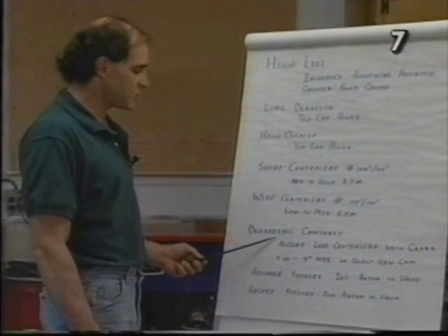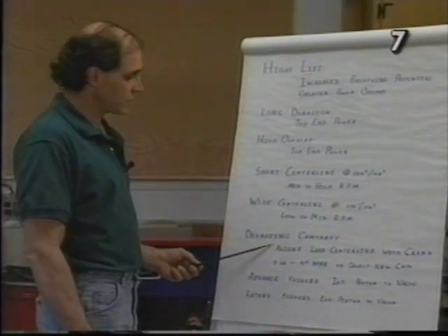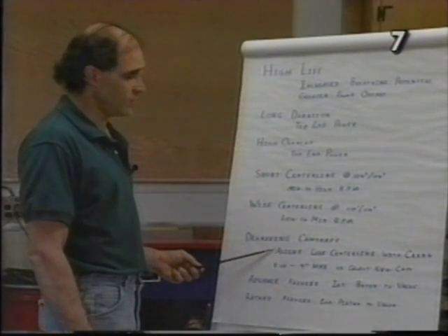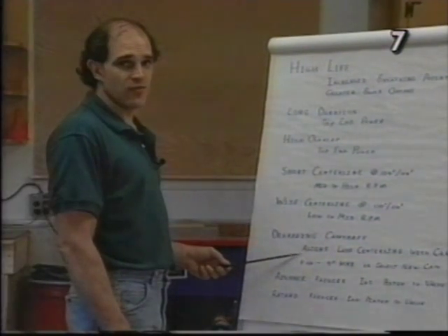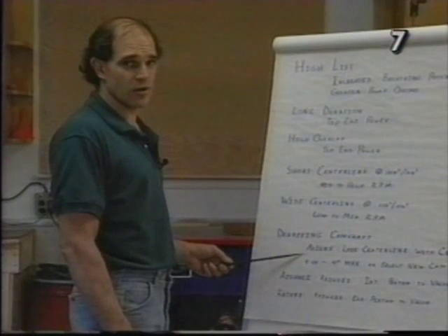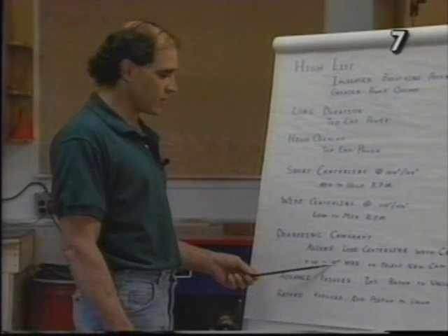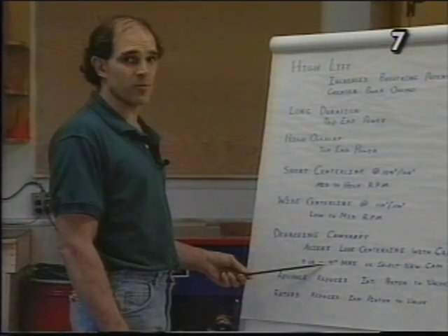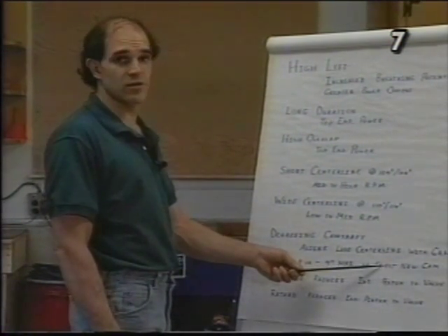When you degree a camshaft, you're actually aligning the position of the center line of the intake lobe with the crankshaft. If you find that you've had to advance or retard your camshaft more than 4 degrees from the manufacturer's recommended center line for proper performance, you should be looking to select a new camshaft.